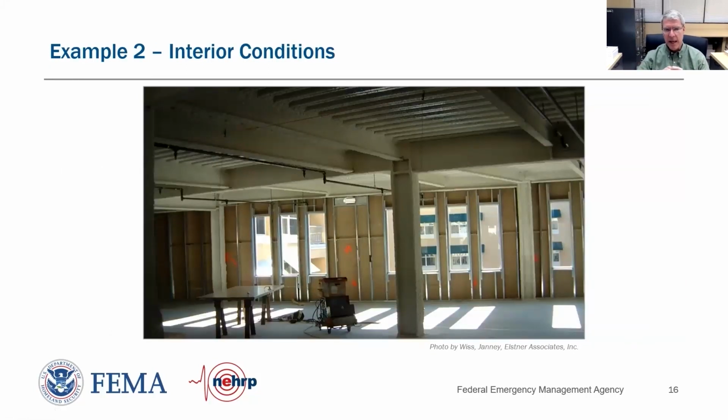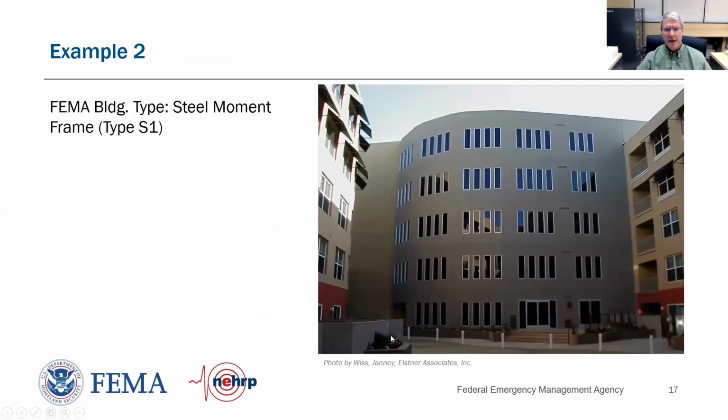And then here's our slide showing an interior view of an unfinished space. And we can clearly see that we've got continuity plates at the bottom of our beam at our column, which is a dead giveaway for a steel moment frame connection. Therefore, we can conclude this is a steel moment frame building, therefore S1. So that is confirmed. We have our building is on the left here in this photograph. The building in the back is a different building, not part of ours. There is a separation we can see clearly on the left.